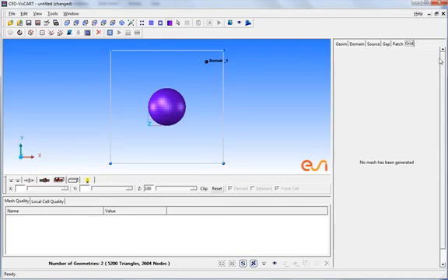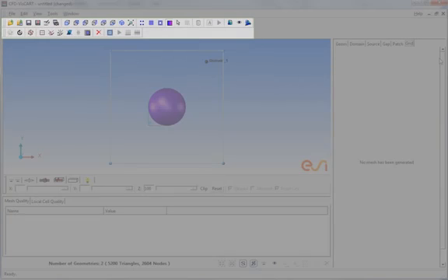Let us go back to working with CFD-VisCART. The bounding box serves the purpose as explained in the schematic. The domain marker serves to identify the region that needs to be meshed. For example, the current location of the domain marker implies that the mesh needs to be generated around the outer sphere, not inside it. The CFD-VisCART toolbar includes shortcuts to the most frequently used functions.